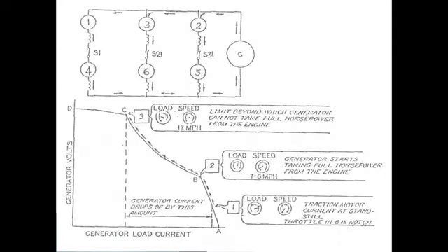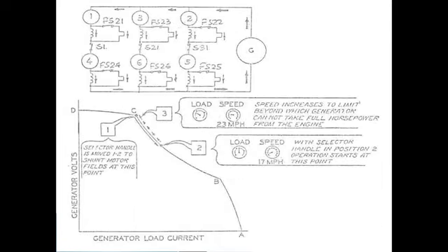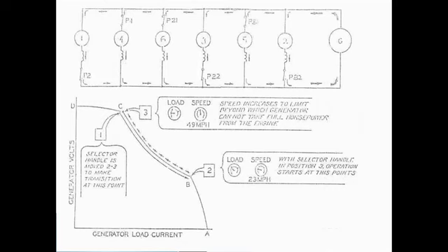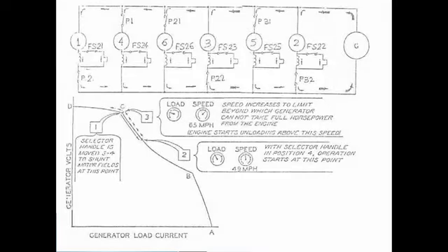Following slides show how the traction motor windings are changed from 2 series 3 parallel to 2 series 3 parallel shunt. In this case, shunt resistance provides an alternate path for the current to pass and hence the back EMF drops, in turn increasing the speed. Again, at a certain speed, the windings are changed to parallel and finally to parallel shunt. The whole process is summarized here.